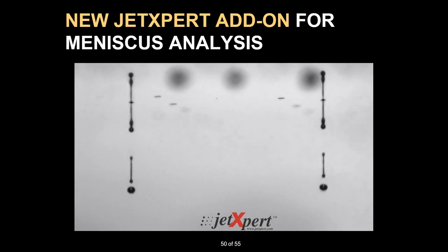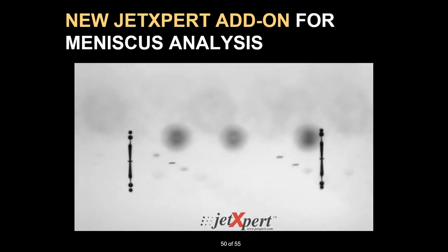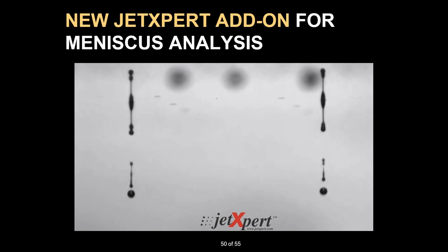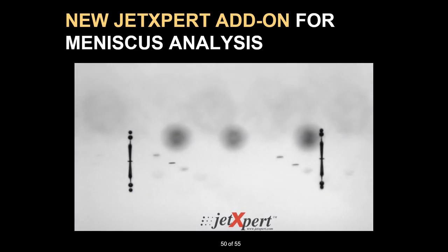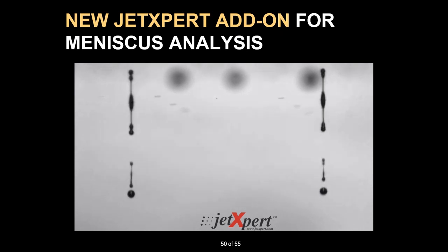Something else that is a new feature of our product that comes into play here is that we've modified the ImageXpert system so that it's able to look more directly at the nozzle. This is helpful as you're optimizing the waveform, because between every drop that's actually being ejected, there's a little meniscus of activation. This is a helpful tool for creating a tickle pulse or optimizing the waveform, or if you have a problem with wetting that you can't necessarily explain, something like this could possibly help explain it. That's a new feature that makes sense to mention at this time.